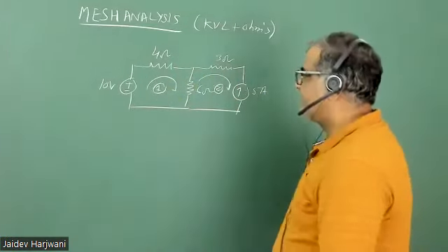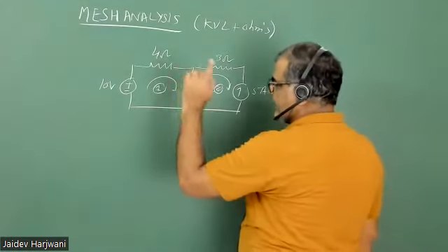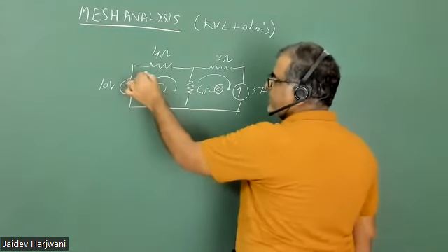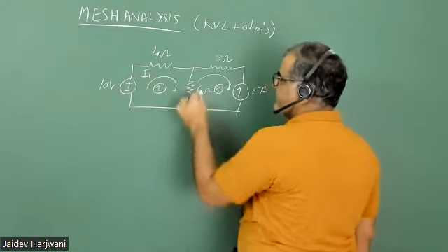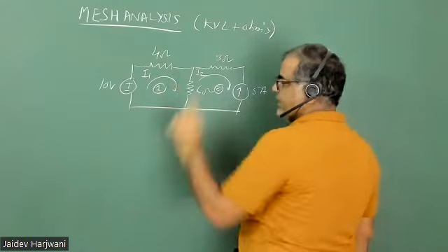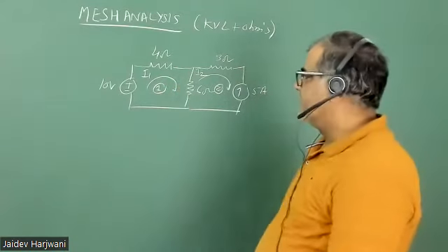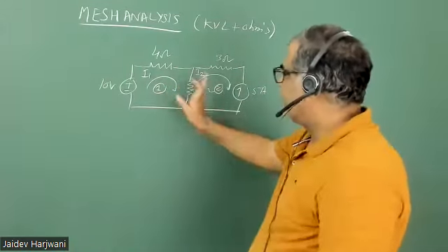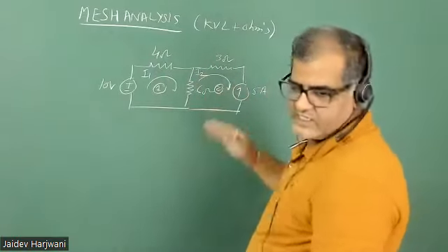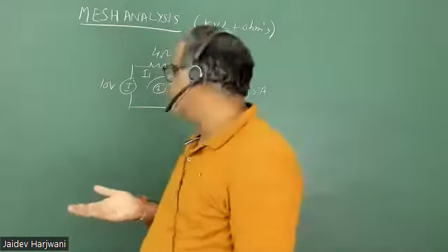Okay, now the next thing is the number of loops is the number of currents. Okay, assign an unknown current. So see, unknown current here is I1 and unknown current here is I2. Okay, so current is done. Now you know which direction you are moving, and current always moves from higher potential to lower potential.